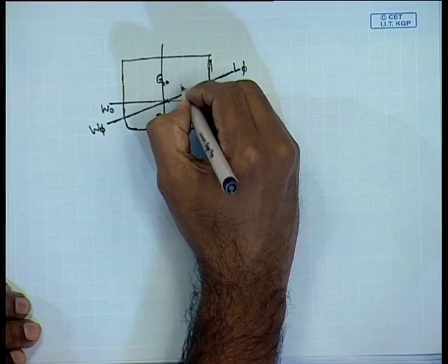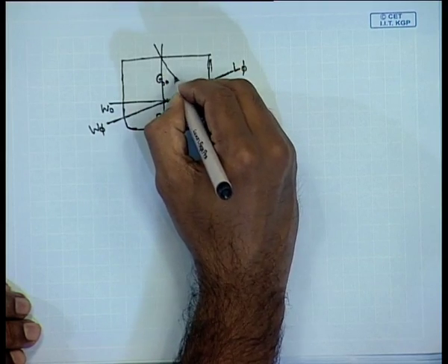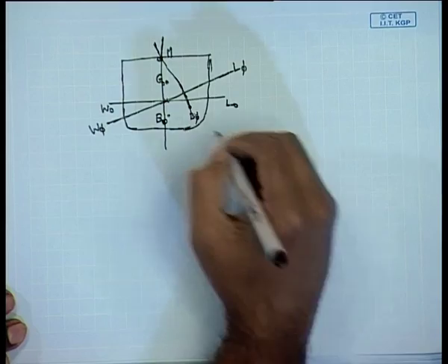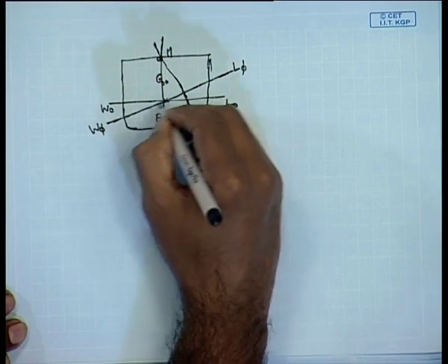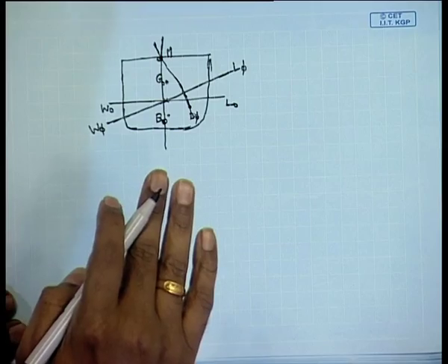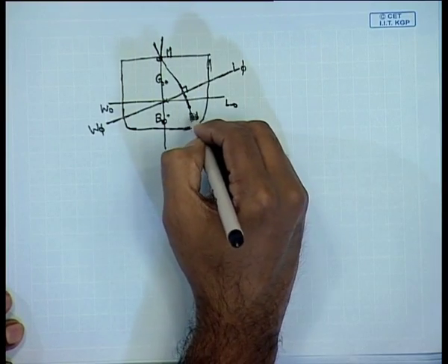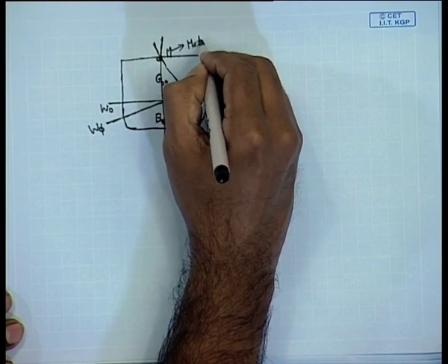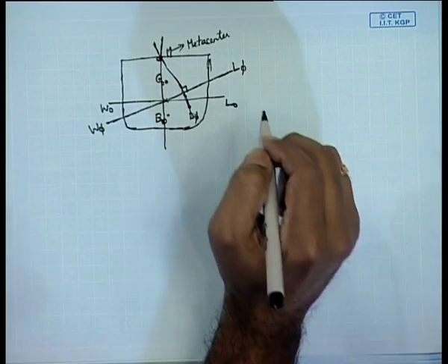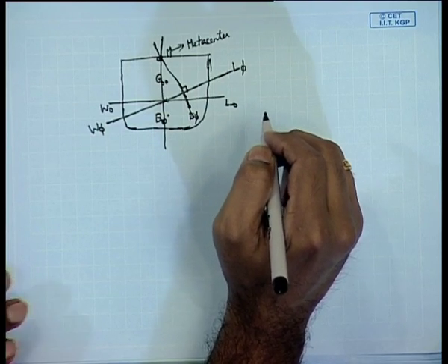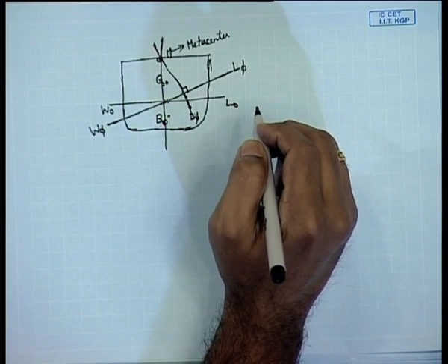If you draw a vertical here, this hits the original vertical. Remember, this line is vertical because W phi L phi is a horizontal line, not vertical, and perpendicular to that it is always the vertical. So B phi M is a line, and this M is known as the Metacenter, a very important concept in naval architecture. Metacenter point M.